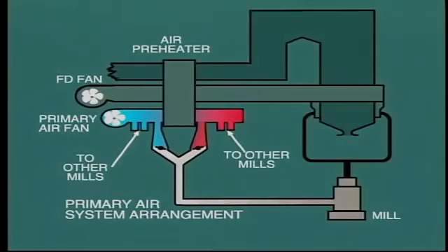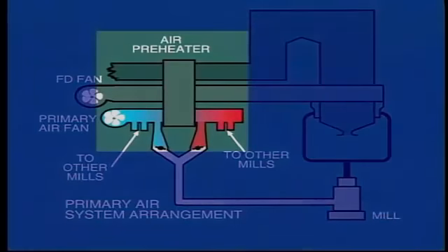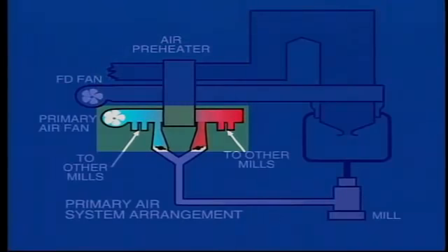In order to avoid this, some effort is made to dry or partially dry the fuel before it enters the furnace. One way of doing this is to heat the primary air so that evaporation of the moisture takes place before the mixture enters the furnace. Often, a dedicated hot section of the boiler air heater is applied specifically for this purpose.